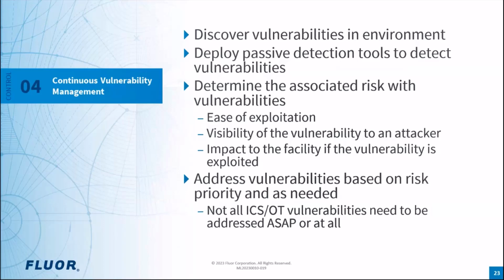Well, let me take a step back before I get too far ahead. The idea is that in OT environments, we want to know the assets we have, and we want to know the vulnerabilities. In IT environments, if we have a new vulnerability, we typically run around like chickens with our heads cut off and try to patch all the servers and all the workstations and all the other things in just a couple of days or a couple of weeks. In OT environments, it's very, very different. Just because there's a vulnerability doesn't mean that we need to jump into action right away. So when we discover a new vulnerability, we look at the true risk associated with that vulnerability to determine if it needs to be addressed.